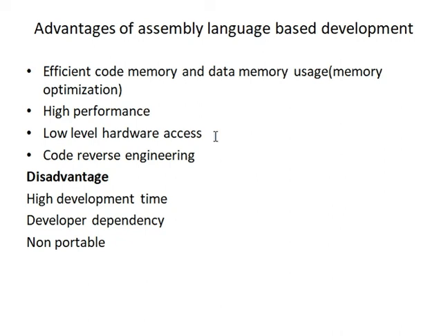For addressing the priority, you have an interrupt enable register wherein you can define the priorities too, and also enabling or disabling the interrupt can be addressed in this register. And these registers, which are basically for a Cortex M3 machine, could be addressed easily using assembly code.